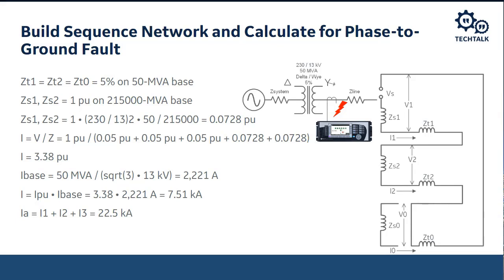And so we can see there in this particular example that by ignoring the system impedance, or assuming an infinite bus on the system impedance, that basically essentially doubled our fault current in this particular example. Won't always do that. In most instances, your transformer will be the limiting thing, but for my example today, it cut it in half. So it's worth doing that if you can get the system capabilities.